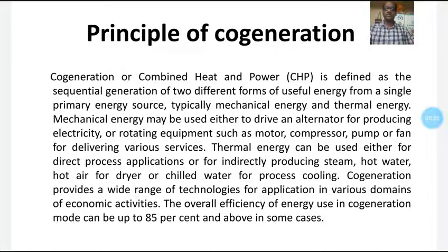With 40% as the first cycle efficiency and 30% as the second, the overall efficiency is nearly 58%. The thermodynamic relation, in simplified form, is eta overall equals eta 1 plus eta 2 minus eta 1 into eta 2.